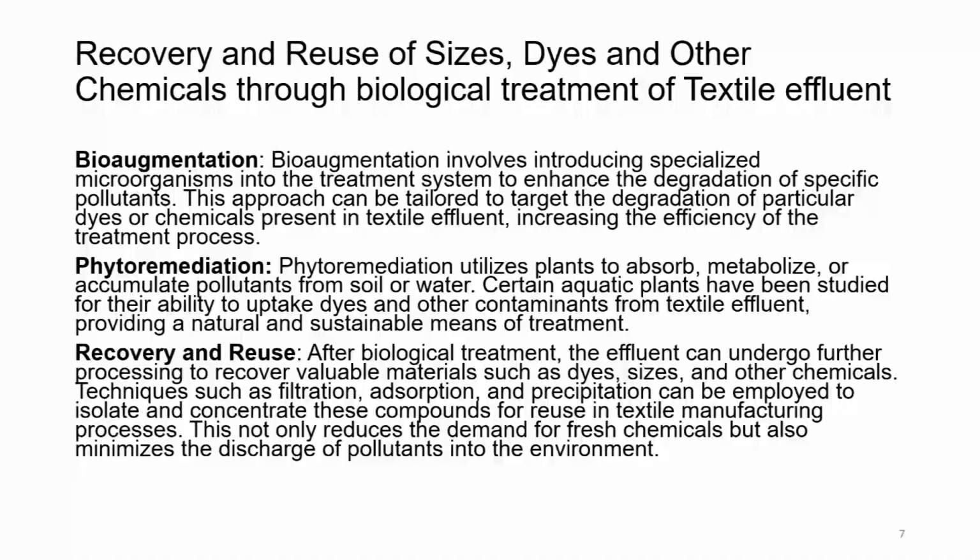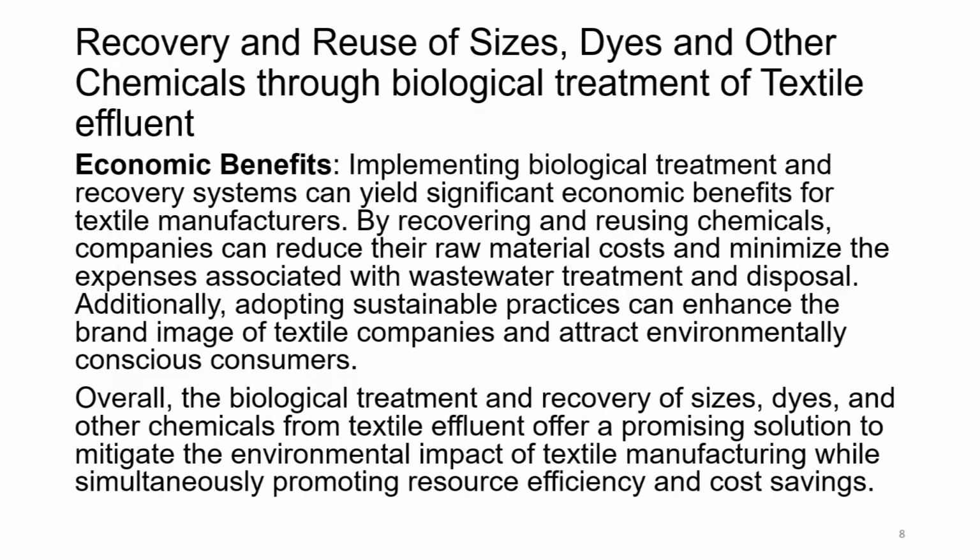The dye bath cannot be thrown just like that, because it is very enriched in dye still, and this can be reused by adding or dosing sufficient amount of concentration of dye, so that the initial dye concentration is reached and the dye bath can be used for second time. So, this is the kind of phenomena that we are emphasizing in this lecture related to recovery and reuse.